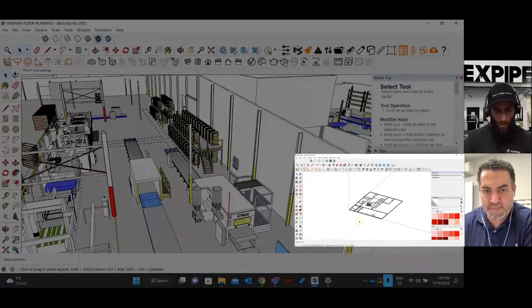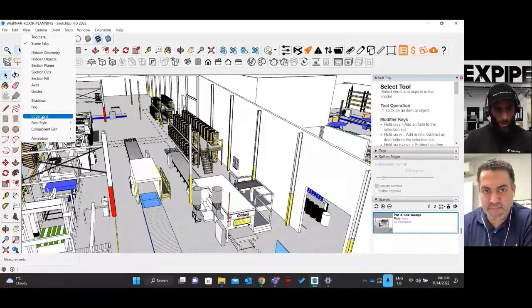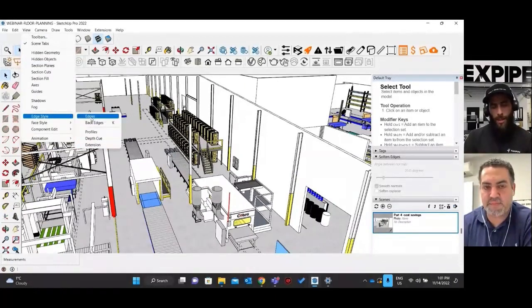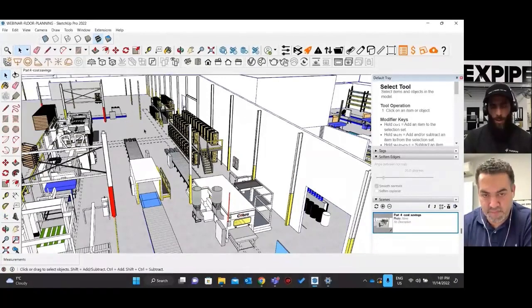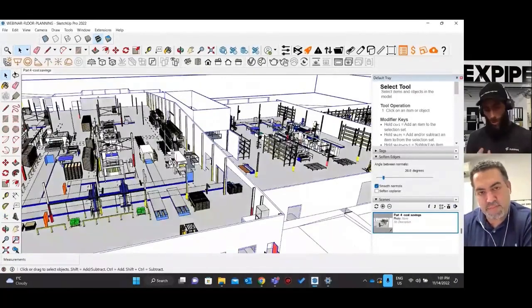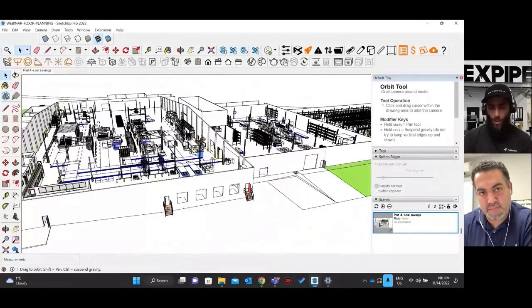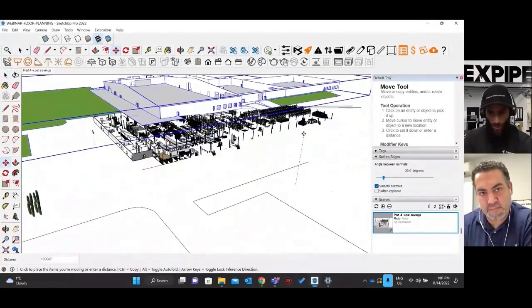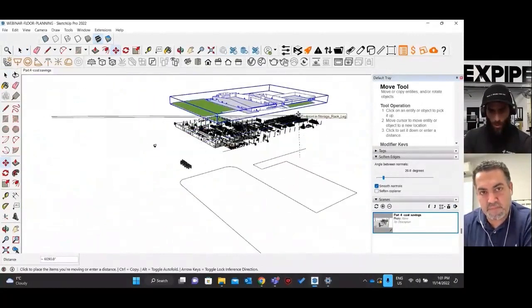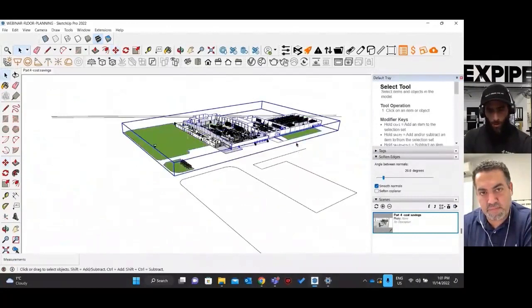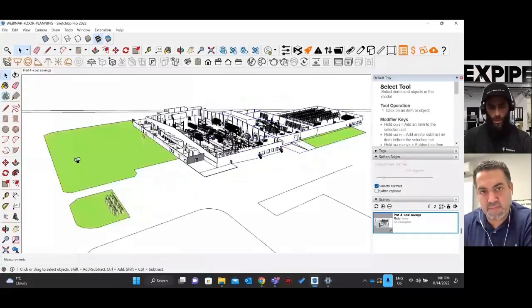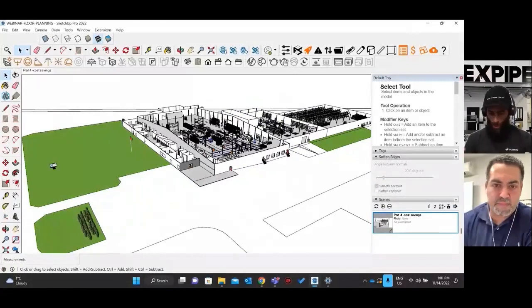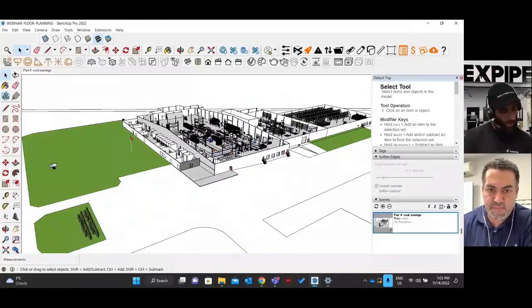So a lot of the little tips and tricks also could be coming here and thinking about the edge style, and maybe deselecting a couple of the other ones so that it's not as demanding on SketchUp, right? But again, one of the main reasons why we're adding those components is to minimize those file sizes as well. And then from there, you're using different groups, right? So we can see here as I begin to move up, I'm able to separate the different parts. So again, these different groups are making all this happen. Just a bunch of individual puzzle pieces that can help you out, right?